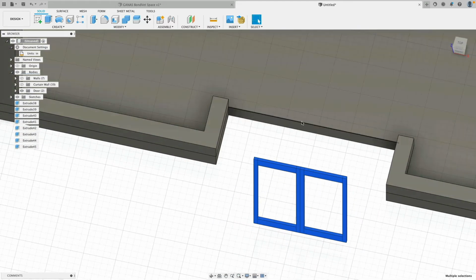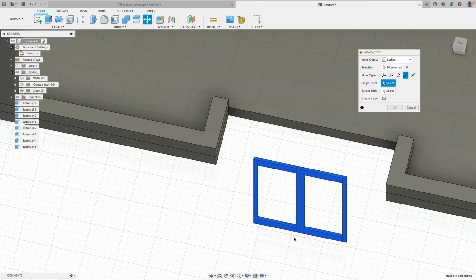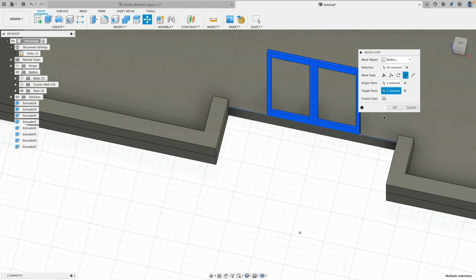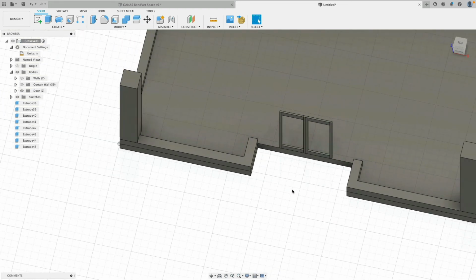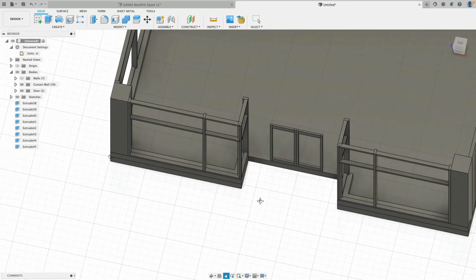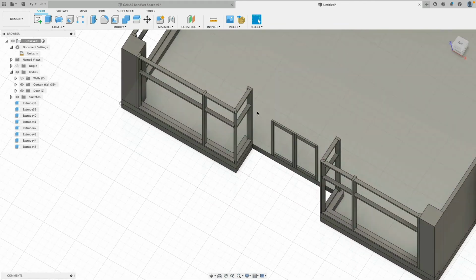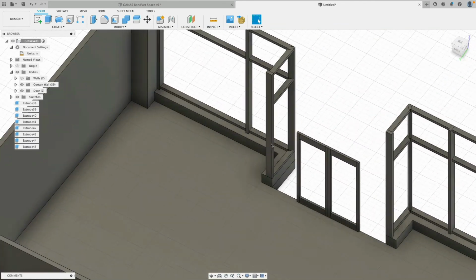Okay, so now we want to snap this to there. So we go to the move command, from this point to, and look, there's the midpoint to that point. Zack. And our door is positioned. Beautiful. So what can we do now? We basically know exactly where this is, and we have to build the frame that goes around it.